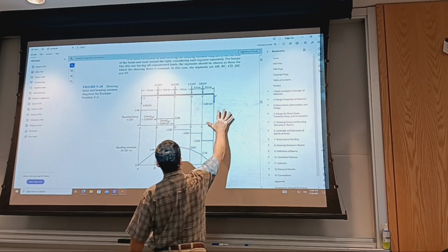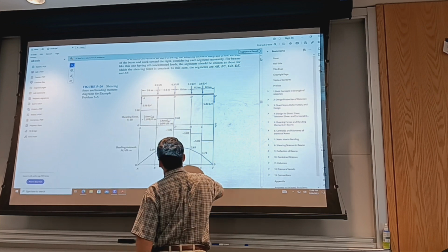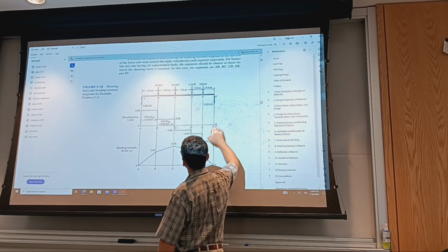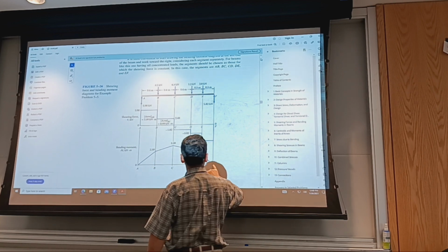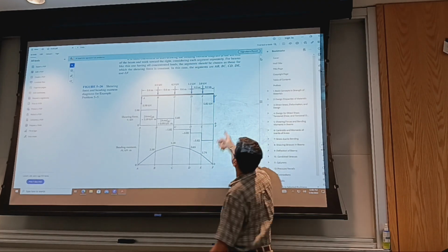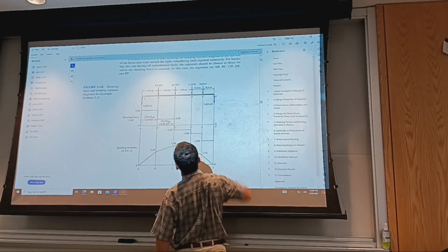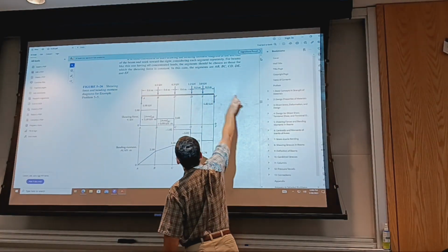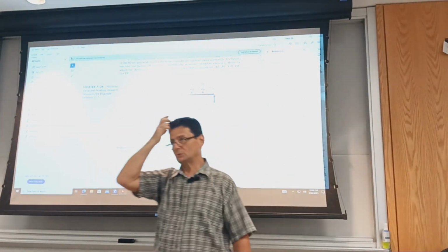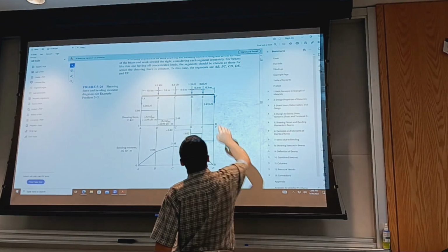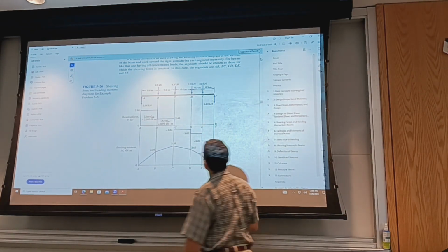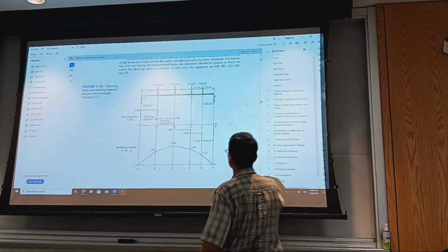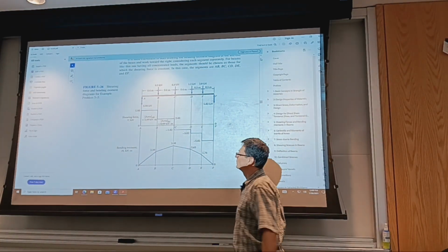You should verify that the reactions of the supports are correctly calculated. So the shear diagram will close to 0, and the moment diagram close to 0, unless there could be a case where I have a concentrated moment at the end, in which case it closes to 0 only after I pass there. After I pass the end, you can assume a fraction of an inch past point F, then it should be an unloaded portion of the beam. Diagrams all will go to 0.